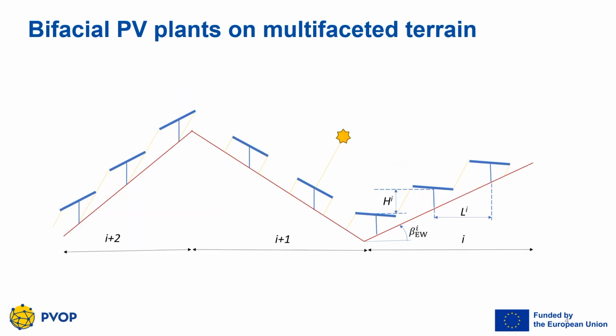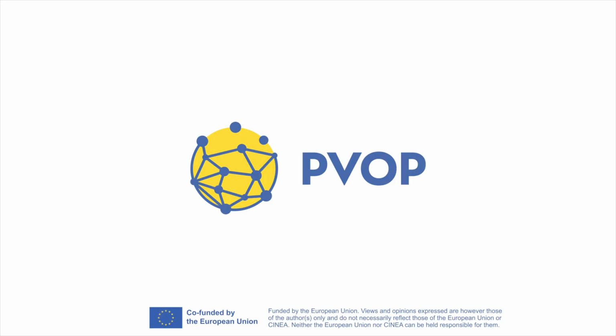In conclusion, this model and tool allows us to simulate bifacial plants with all 3 degrees of freedom. This means we can use terrain with any north-south and east-west orientations combined, and with tracker axis aligned in any orientation. Furthermore, we can move the calculation of the backtracking angles to the control of the real PV plant trackers. This also works in multifaceted terrains.